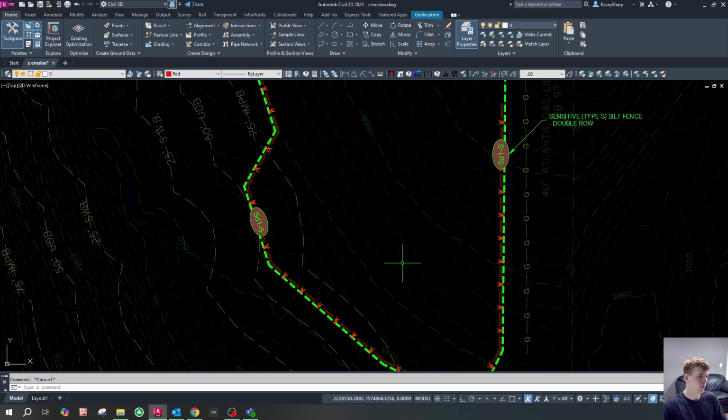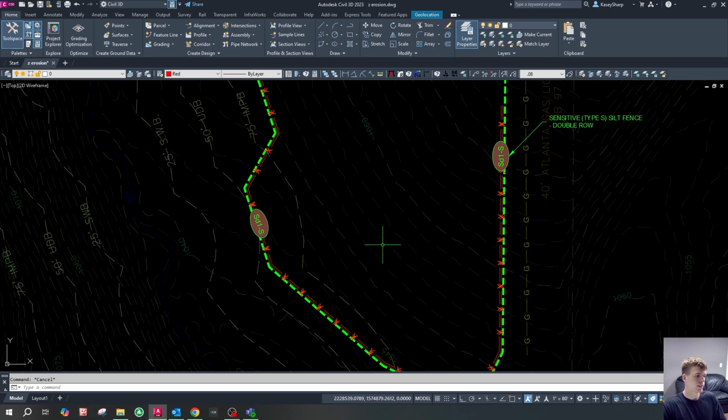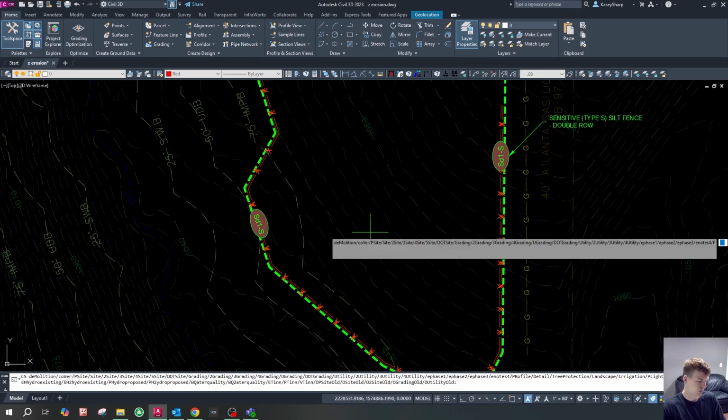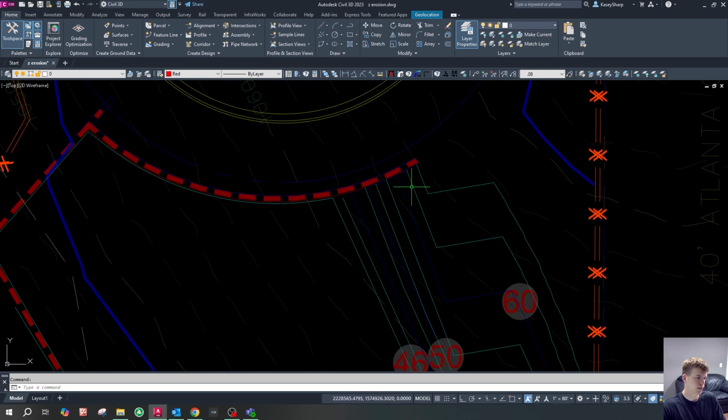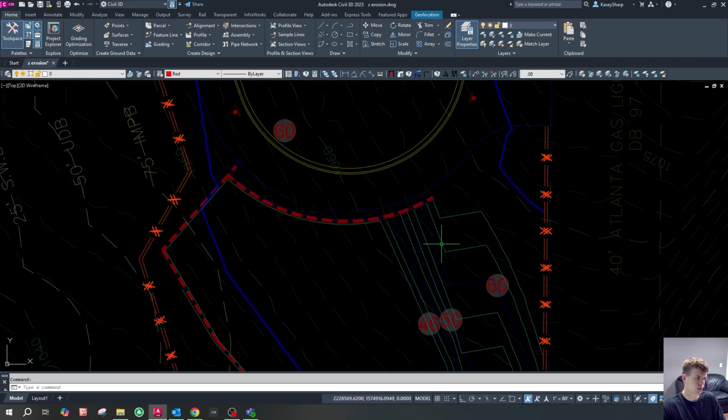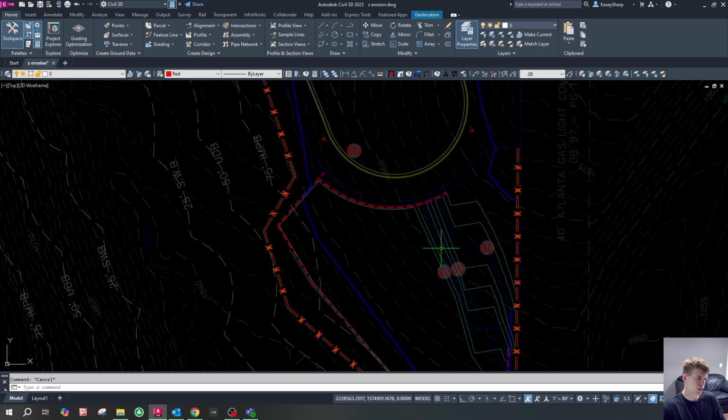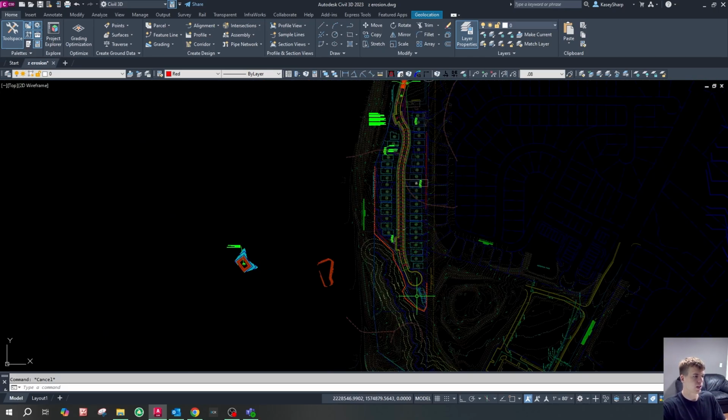If we keep the bottom of our sediment trap above that, then they're not going to have to fill anything in. I'm going to go back to our phase 2 here, and the top of this detention pond is roughly, there's the 60, so 62, 64. So from 46 to 64 is the bottom and top of our detention pond. For our sediment basin, we can keep it within that range, so they won't have to do any extra work when grading out the detention ponds.